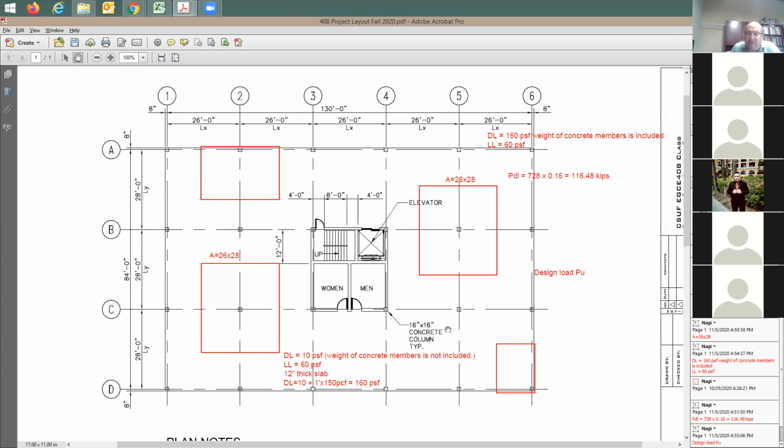Also, you're going to have a footing design. I'll give you the axial load, footing dimensions, the depth, the rebar size, and I'm going to say design the rebars. Also, you need to have the one-way shear check, and also the punching check at the column. And maybe a couple of simple problems, like multiple choice, so that you can gain some points in an easy way.